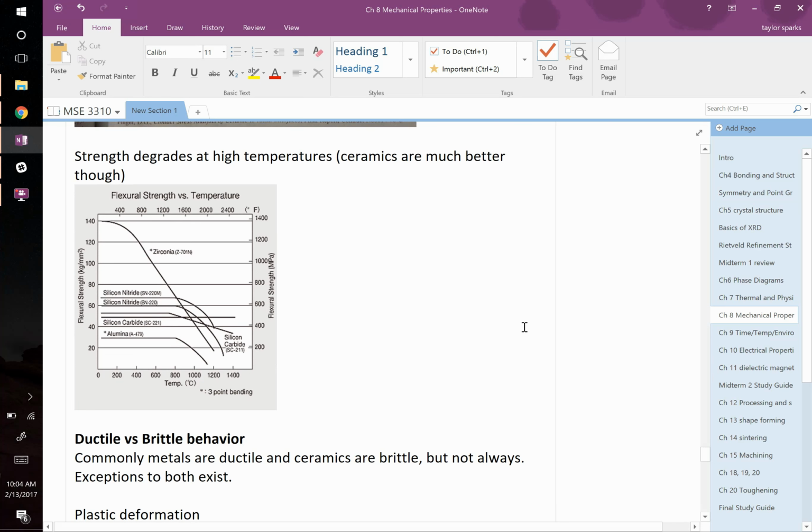It's this game we have to play because on one hand, let's say that you have a big gouge in your material from something. You know that's going to reduce the strength. It's a huge half crack length right at the surface. So you want to polish it to get rid of that. But as you polish it, you introduce a bunch of really small half cracks and surface damage from the trailing wake. So you have to try and fix that.